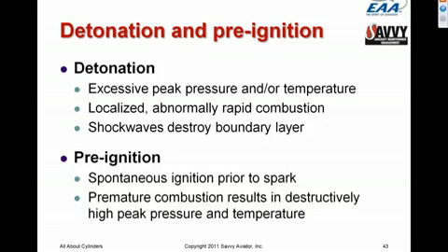We've recently been seeing problems, for example, with Champion fine wire spark plugs where their insulators start to crack. And if a piece of the cracked insulator winds up bouncing around in the combustion chamber, it can serve as a glow plug and create a preignition event that can destroy the cylinder or destroy the piston usually, and various other things can do that. Excessive lead buildup can do that. Other sorts of foreign material that gets into the combustion chamber can do that.